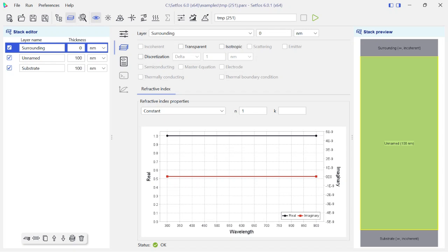Generally, OLED degradation, especially in blue devices, is a major challenge in commercial applications. Intrinsic degradation mechanisms are commonly attributed to excitons and reactions. We also have examples for OLED degradation, but we are directly going to create a new simulation file. We take the layer names and thicknesses, and then I will provide the inputs. I hope you already know the theory part, so we are not covering too much theory. I'm directly showing how you can simulate.